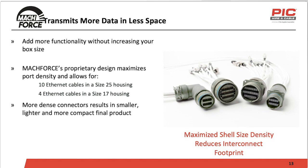MACHFORCE's proprietary design allows you to pack 10 ports into a size 25 shell. Most premium competitors are only able to get 7 or 8 ports into their designs. In fact, the standard D38999 products that use a discrete wire design are only able to get around 4 ports in a size 25. So in some cases, as a design engineer, you may be able to replace 2 or 3 other size 25 connectors with only one MACHFORCE size 25.